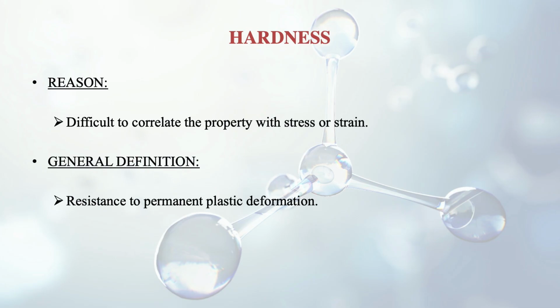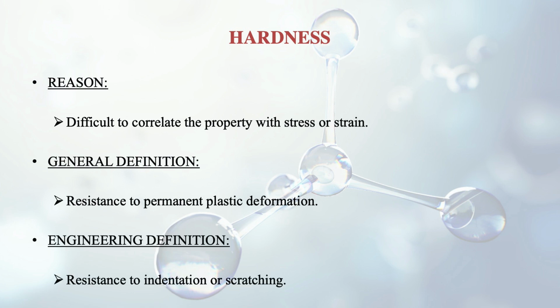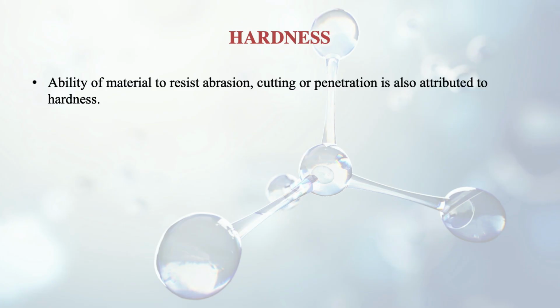And now the general definition I am giving you about hardness. It is resistance to permanent plastic deformation. It's a general definition, and the engineering definition is that it is resistance to indentation or scratching. Like if I scratch my hand, this is related to hardness. Then it is the ability of the material to resist abrasion, cutting or penetration, and we know that this is attributed to hardness. All these things, abrasion, cutting, like we also get abrasions or bruises in our bodies, are similar to that.